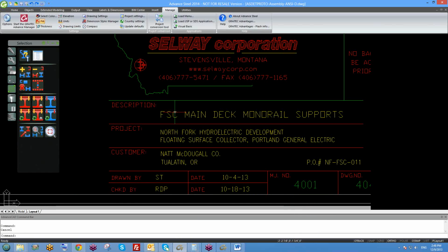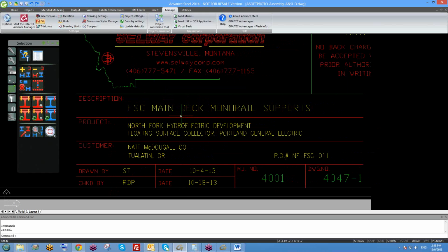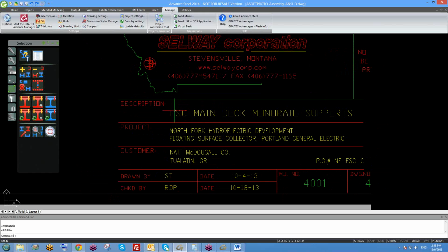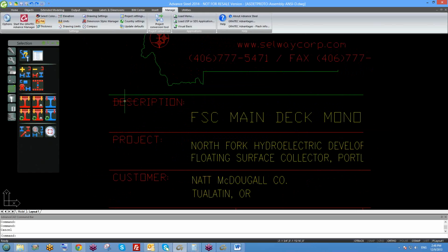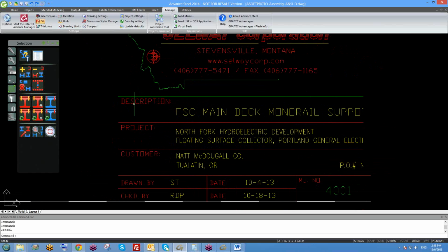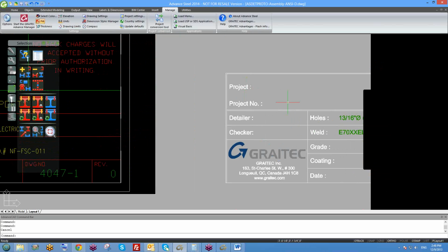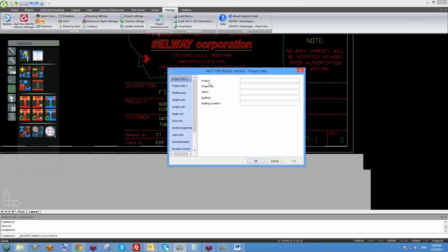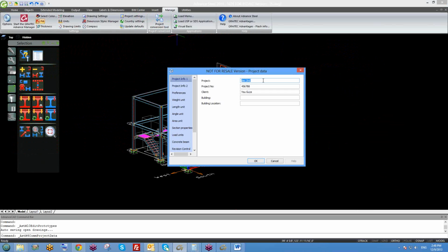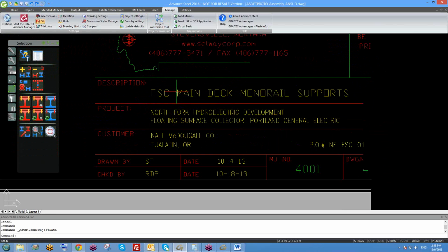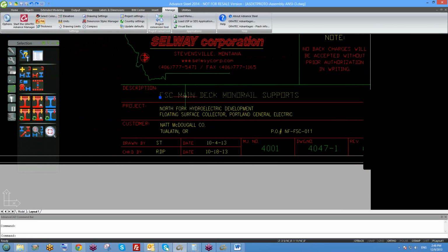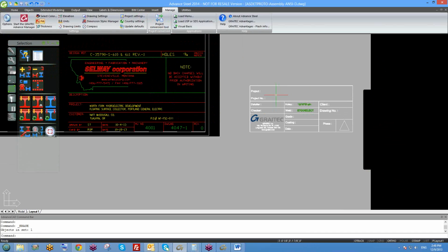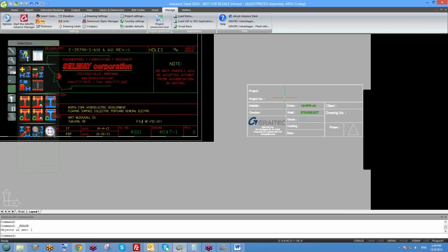Description, I think this is your company, the name of the project. For this project name, this description is fine. This is your internal description, so you can keep that. It doesn't matter. But if you want to get the project name, you put it under project setting on the model. This name here, if you want to get that, you need to delete that and replace it with the tokens used by Advanced Steel.